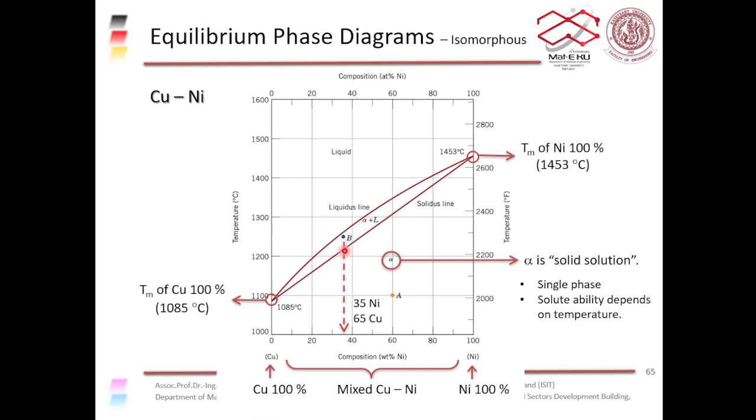And when you get to about 1250 degrees Celsius, at point B here, you get molten metal and a little bit of the solid phase still in there, until you reach a temperature above this line here. Then you would get complete liquid metal, or complete molten metal.